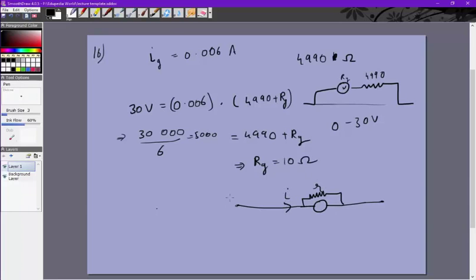So in this case the current is I. That means if this is Rg, the current through the galvanometer is I times small r by r plus Rg. We know this formula, right? This is for parallel. They are divided in inverse ratios. Since r is very small, most of the current will go through it. A tiny fraction will go through the galvanometer, which is proportional to small r. And the range is 0 to 1.5 amperes.